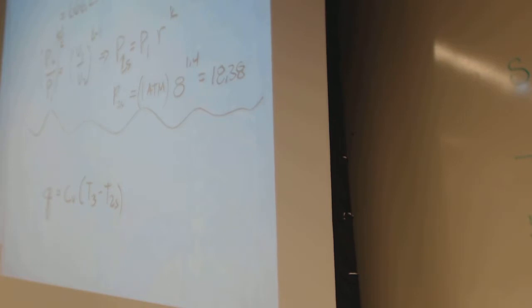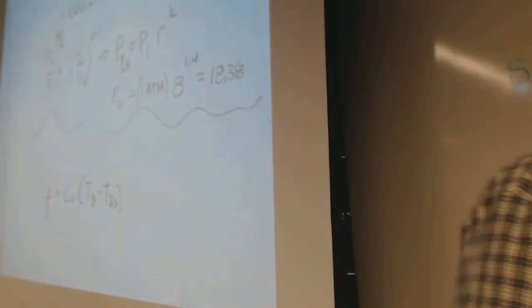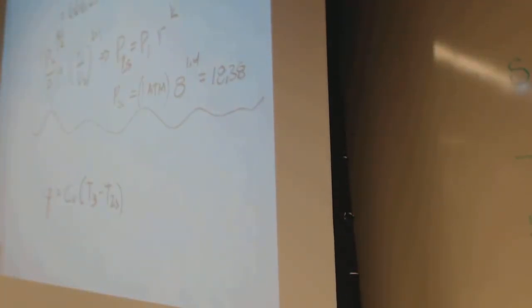That's a pretty good approximation of what really goes on, because 5 or 10 degrees on either side of top dead center, it doesn't move much. So you let off the spark and kaboom, it burns at a constant volume. Now there's no work going into moving anything, so all that energy is going to go into changing the temperature.